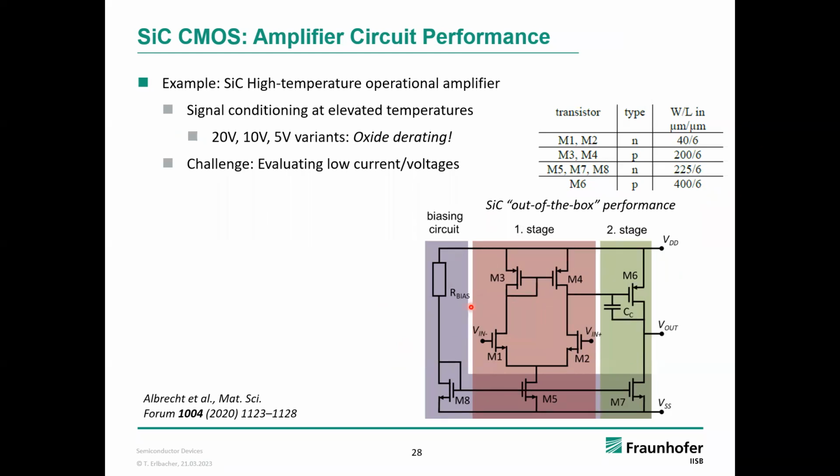And of course, you can also use analog circuits like operational amplifiers, for instance. This is quite helpful if you want to do sensing applications, especially at higher temperatures. Getting signal readings in the nanoamp range from 600 degrees C to a silicon circuit at 100 degrees C or maybe even 50 degrees C can be quite challenging, and some preamplification on the silicon carbide chip is very helpful.